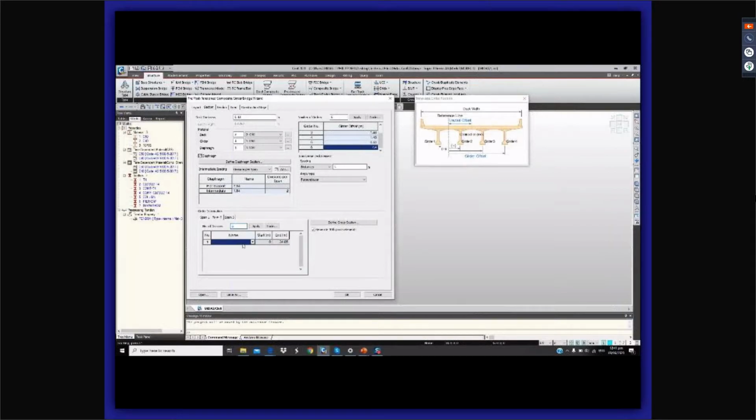And then for the second span, let's set as Super T girders with the closed section. And then for the third span, let's also apply the same, just like the second one. So apply. And then from 0 up to 29.95, set it as the Super T with the void. And then for the last, that is as the partition. Then let's uncheck this one since we already have the transverse deck element per 1 meter.